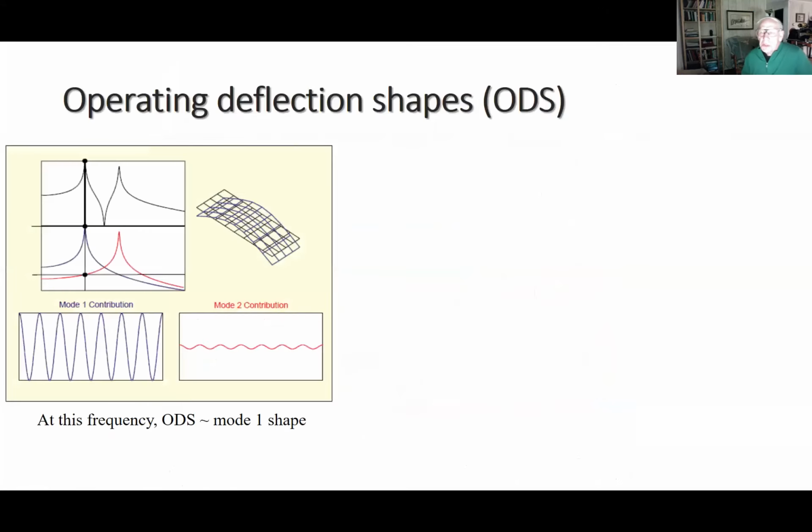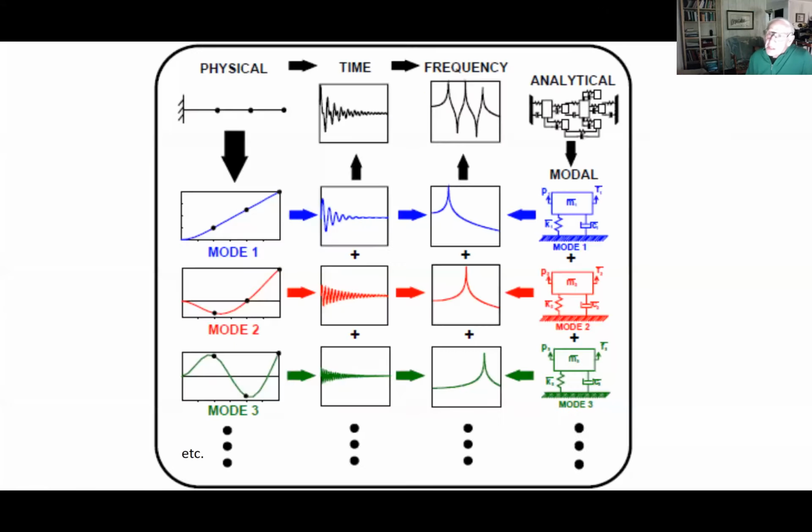The different modes have different effective masses and different effective stiffnesses and different dampings, right? Yes, indeed. Because basically, you need to get the proper resonance frequencies with the proper amplitude and proper damping factor. So yes, it will all be different masses, stiffnesses and damping.